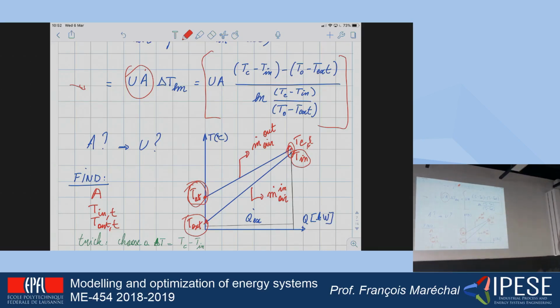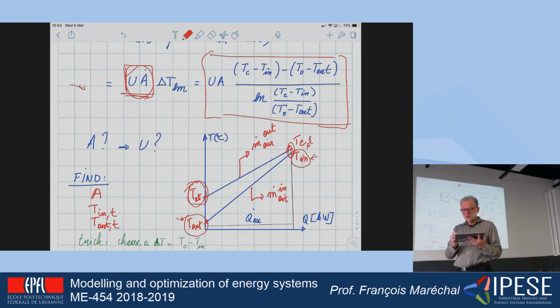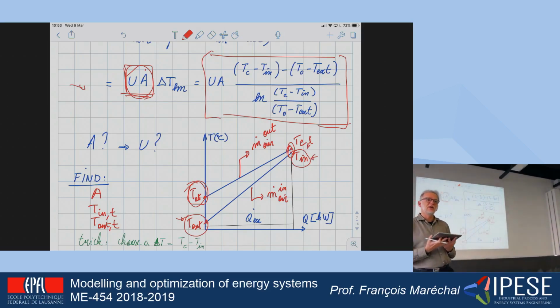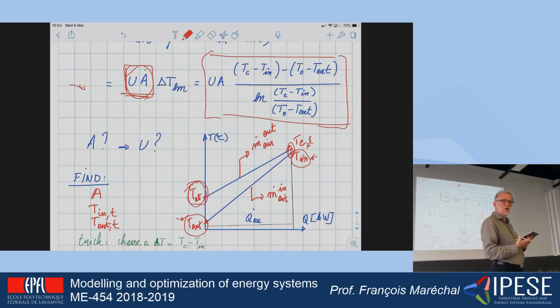But something even more interesting is that for any outside temperature, I will be able to calculate the exit temperature, because this equation is always valid. This will be considered a constant. So for any outside temperature, the Tx that is here, I will be able to calculate the Tin that my heat recovery exchanger will obtain.